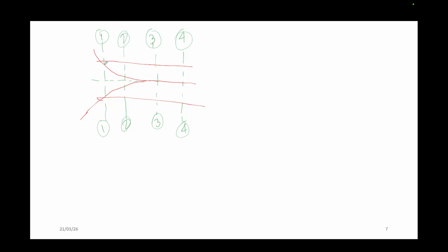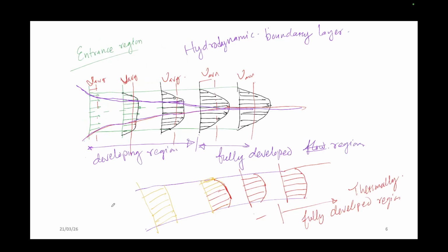The thing is that from the previous one, what we have got is that at the central line, the velocity initially, whatever it may be, because your main objective is that the total velocity or the average velocity should be the same. U average should be the same for this incompressible flow. So whatever the integration of the profile is, that should be fixed.